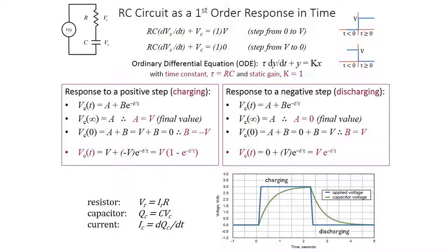We could do a lot of really cool stuff with this once we start being able to filter out selective frequencies or filter out selective impulses. We can start to be able to shape our signals. So again, if you have a speaker system playing music in the background and you have a subwoofer, you don't want to put a lot of high frequencies through that subwoofer because the subwoofer is designed especially to produce low frequency bass sounds. So throwing high frequency through it, A, wouldn't sound good, and B, is a waste as a subwoofer. You buy it to produce those larger, deeper sounds.